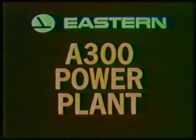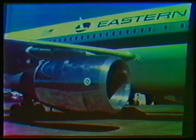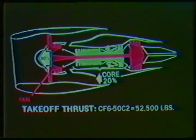This presentation covers the A300 power plant. Eastern Airlines A300 aircraft are equipped with 2 General Electric CF6-50C2 engines. They are dual-shaft, high bypass ratio turbofan engines. Takeoff thrust is rated at 52,500 pounds up to ISA plus 15 degrees. 80% of the thrust at takeoff is produced by the fan, the remaining 20% by the core engine. Each engine is equipped with a fan section thrust reverser.